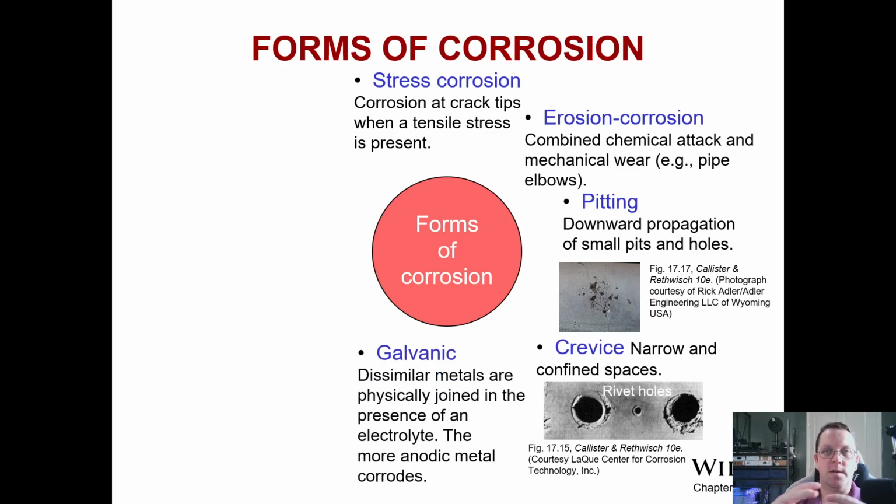The galvanic type corrosion involves dissimilar materials that have some sort of electrolyte in the middle, usually water in the form of rain. Even though rain doesn't always necessarily contain a lot of ions, salts, and other things, there can be examples of acidic rain, where the rain is pulling other components, solubilizing gases and things from the atmosphere. Certainly that's a thing, and that's present in a lot of the smog heavy areas of the country and of the world.